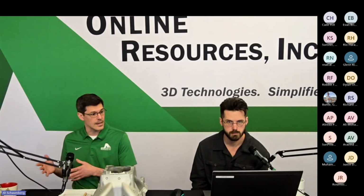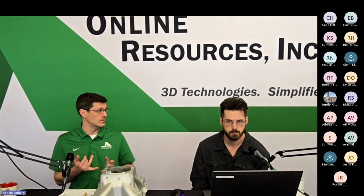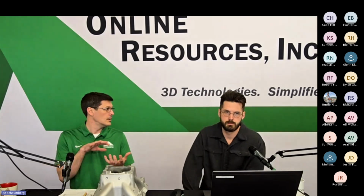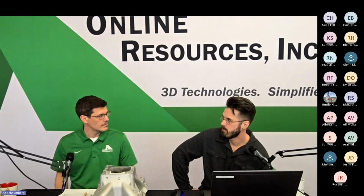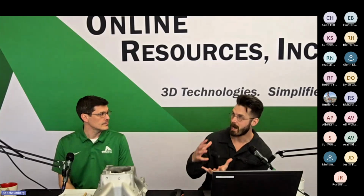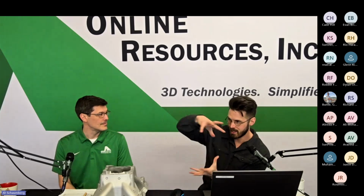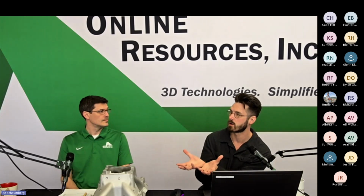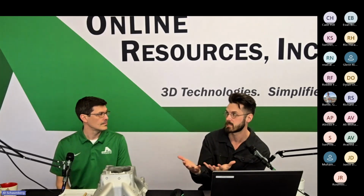So if you have very specific needs, specific questions to your process, some of the things we didn't talk about today was everything we've done here could be done on patterns, corners, and analyzing the core to the final part. Yep. We've done plenty of stuff like that in the past, for people who do the sand printing, taking the core box and scanning both halves of the core box, putting those together, deleting all of the external surfaces so that you're left with the inside surface, and then modeling that so that you have the actual core from the core box. So instead of scanning the core, you can scan the core box halves and get the core as a model to have printed.